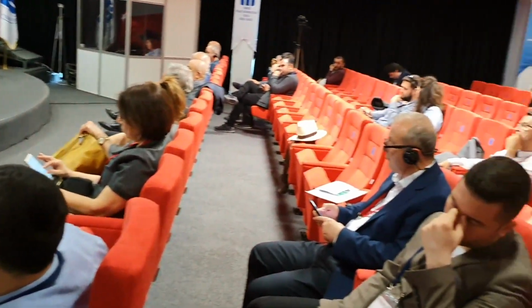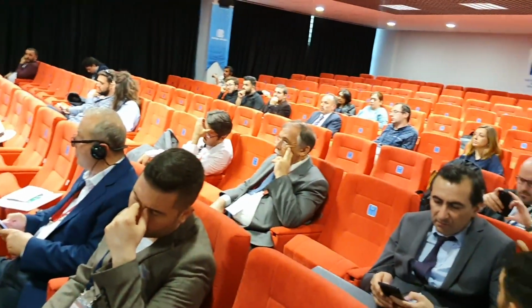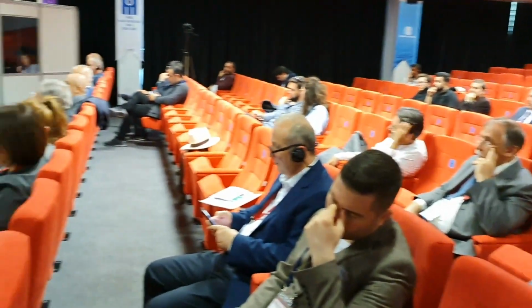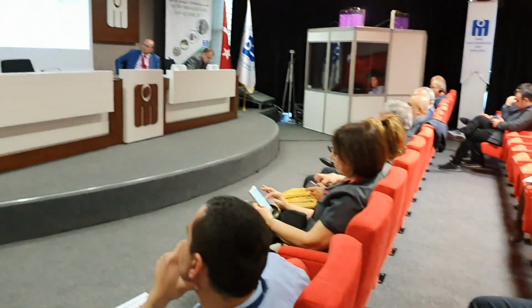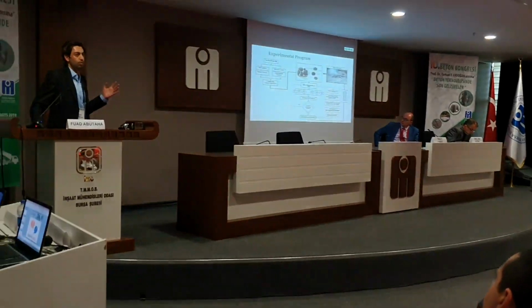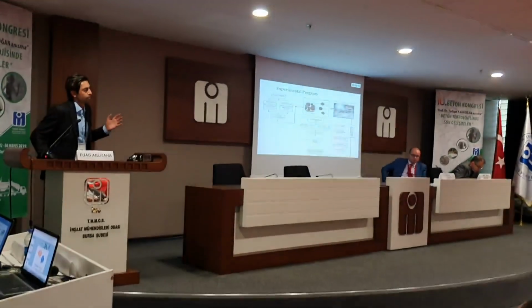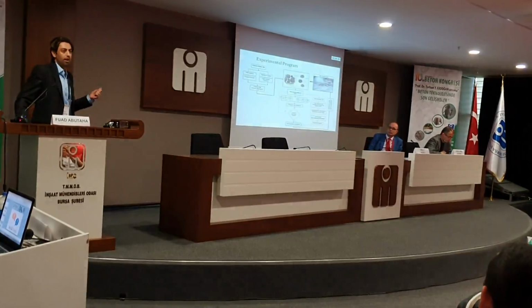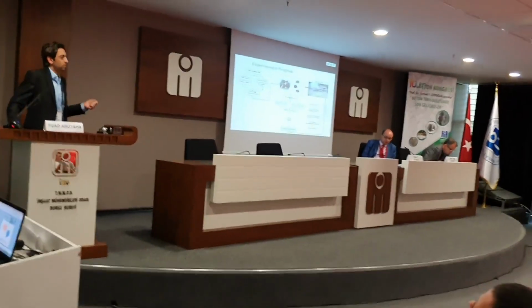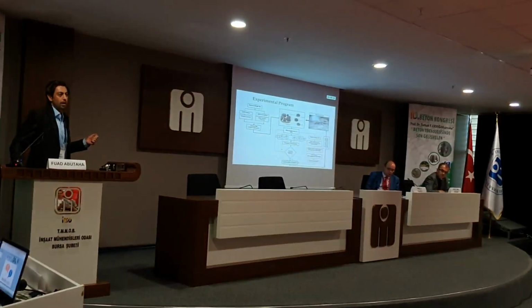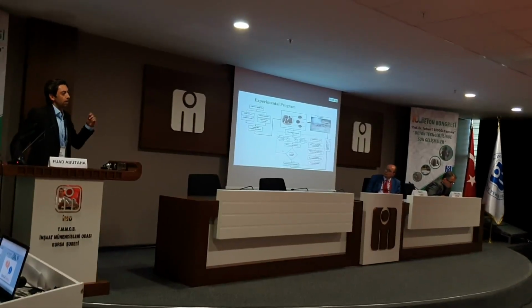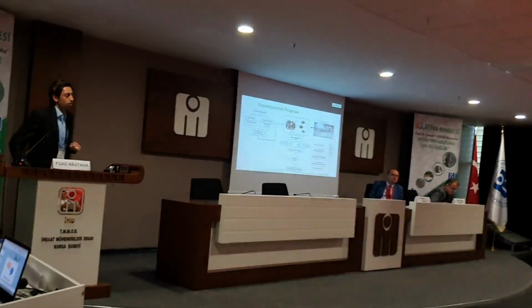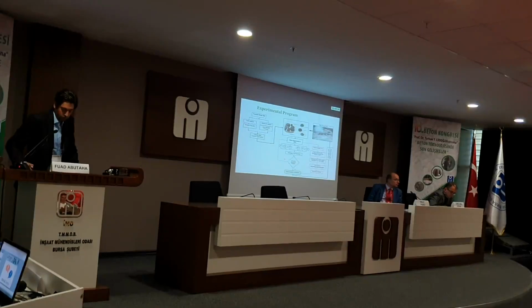Initially we used this material as coarse aggregate, and it had a negative effect on the fresh and hardened properties, attributed to its natural porosity. Then the same material was ground and incorporated into the mixture to fill up the voids of the concrete.